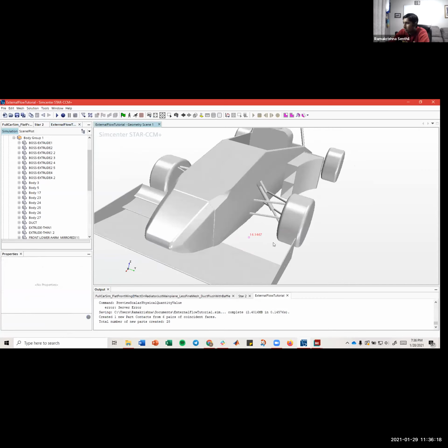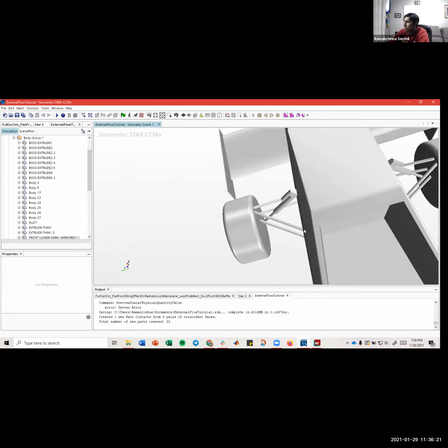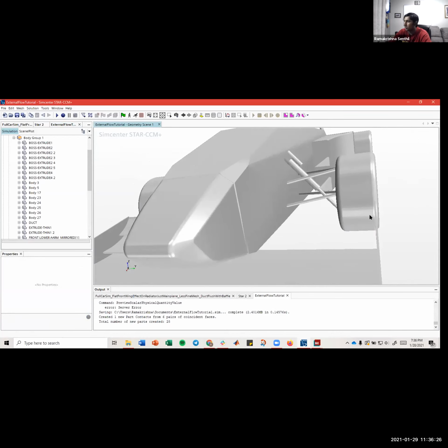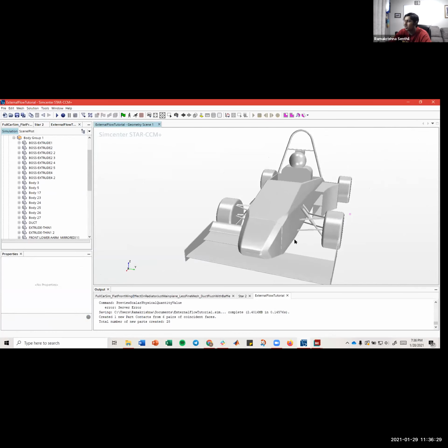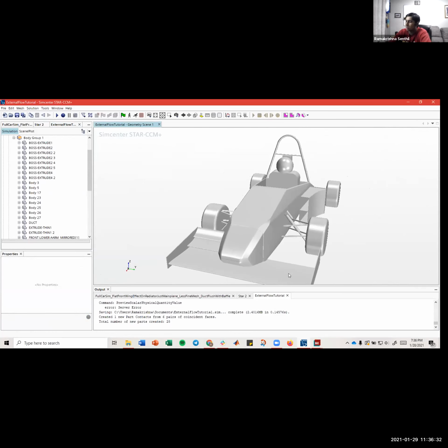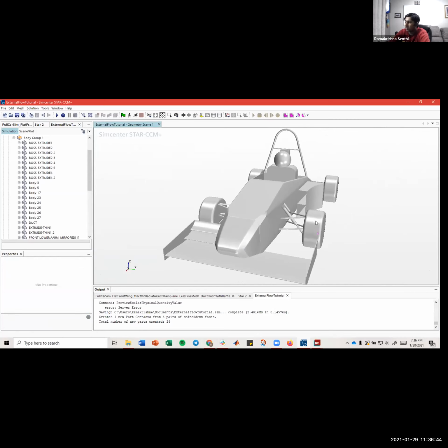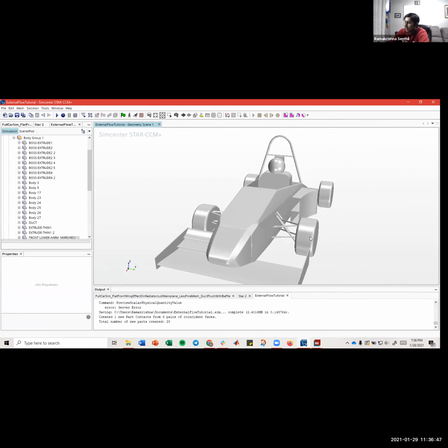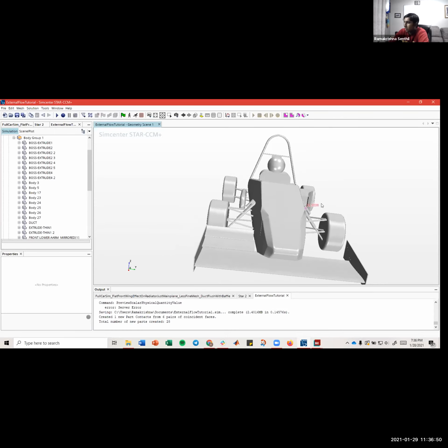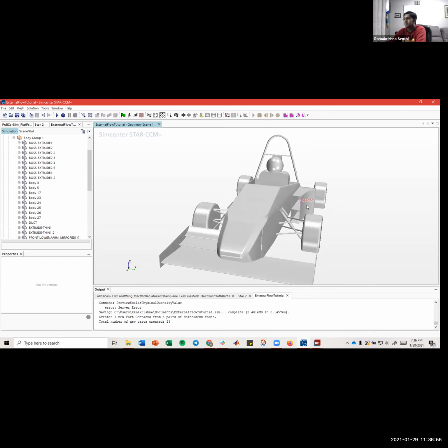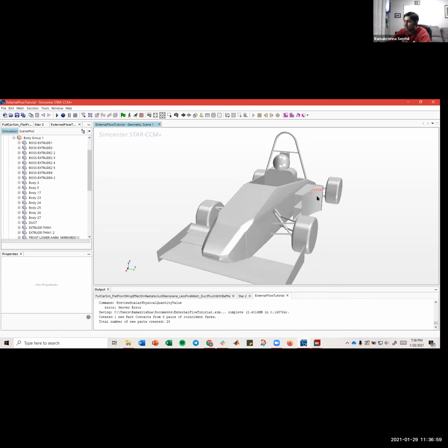And the reason I'm only deleting the ones from the left side of the car is because, as you'll see in a second, we only really need to model half the car because the car is symmetric. So we can just multiply the forces on our airfoils and on the body of the car by 2, and we get our expected value for downforce or whatever it may be. But in the case of the radiator mass flow, nothing really changes. So that's even simpler. We don't even have to multiply anything by 2. We can just measure the mass flow directly.